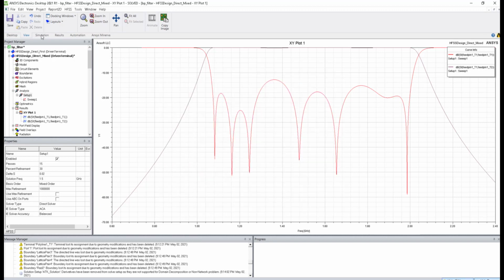So these all are my suggestions for simulation. First of all, update your version. Second one is choose what should be your S parameter accuracy. 0.02 is sufficient for filter and antenna problems. 0.01 or 0.005 is used for signal integrity problems where couplings are on the order of -60, -70 dB. And use